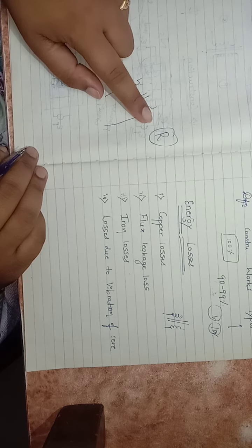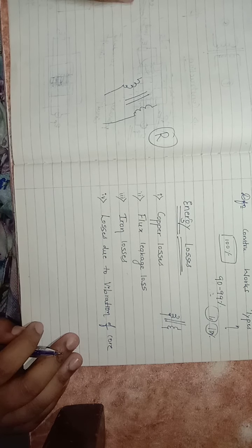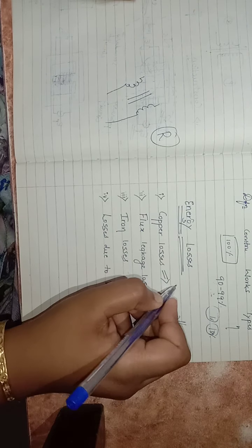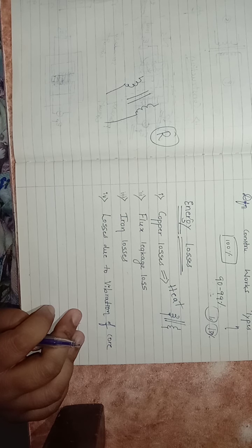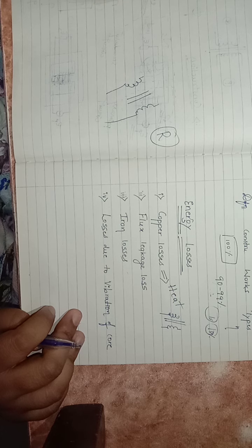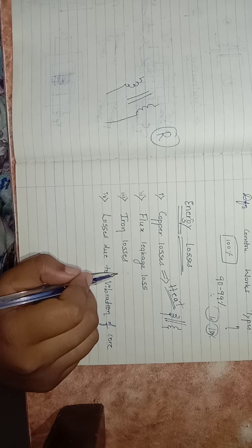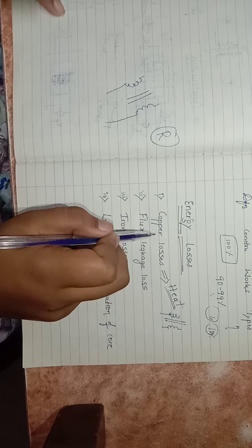So because of that resistance R, whatever current flows in these copper wires will feel an energy loss. That takes place as a power loss, and that loss comes out in the form of heat. The loss that happens in the copper coils of the primary and secondary coil appears as heat. Understood? That is one type of power loss, and it takes place because of the copper primary and secondary coils. Hence it is called copper losses.